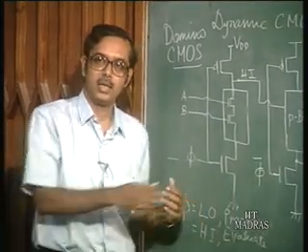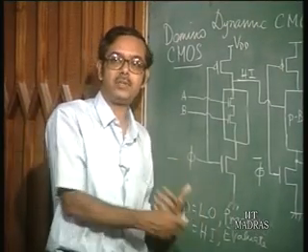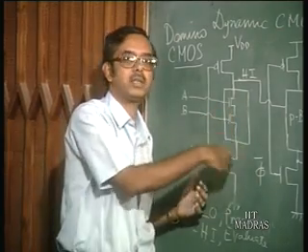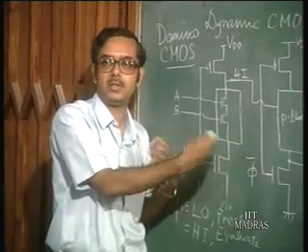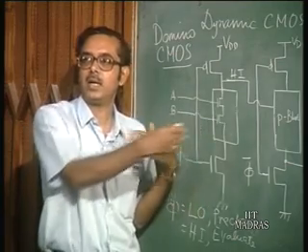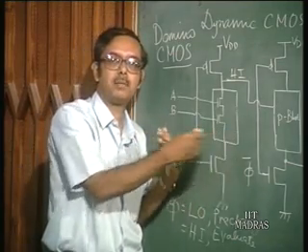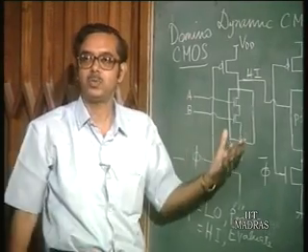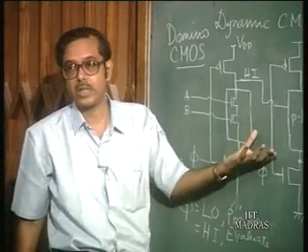So this pre-charge evaluate phase must be quick enough, so that before the charge decays, you have the next pre-charge and evaluate. This evaluate phase or the pre-charge cannot be too long. Otherwise the output voltage is going to change.